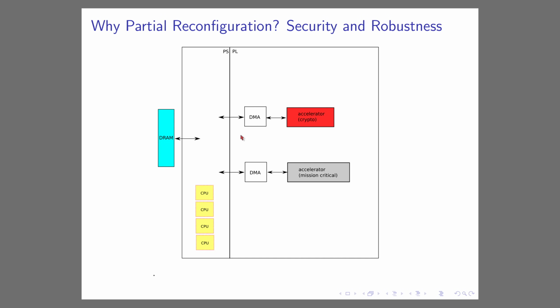For example, I have an encrypted bitstream for this hardware accelerator. Using that encrypted bitstream, I only reconfigure the FPGA when I want to calculate the cipher, and other times I reconfigure the FPGA in this area to have a dummy accelerator which does nothing. This way I feel more confident with my hardware accelerator. I feel more confident because it's not always present in the hardware. It's only and only present when I need it, and other times it fades away.